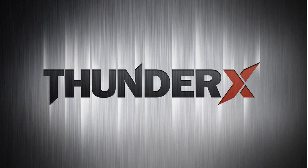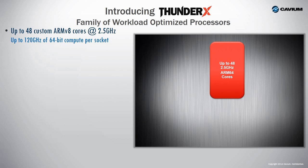So if we start looking at the chip, what we've done with this ThunderX processor is at the core of it, there's up to 48 ARM v8 cores. So these are 64-bit cores. Cavium is an architecture licensee. If you're familiar with Cavium, we've actually put out a 48-core MIPS 64-bit processor in the past. But for the data center applications, due to some of the software ecosystem, we've made a significant investment to also add ARM into our portfolio.